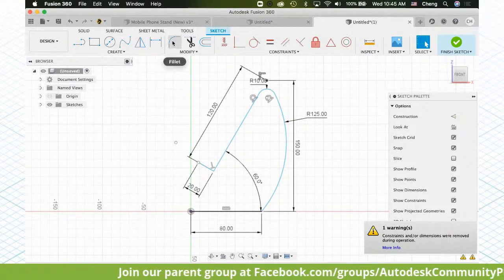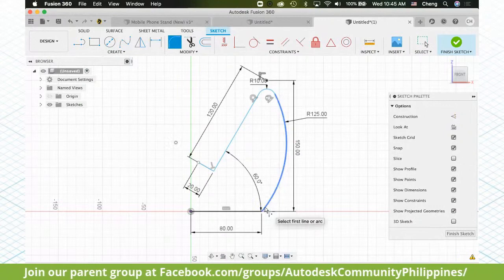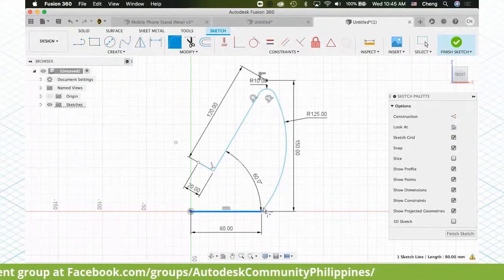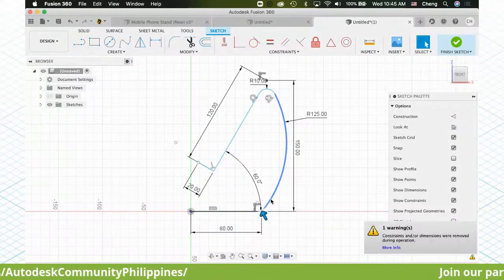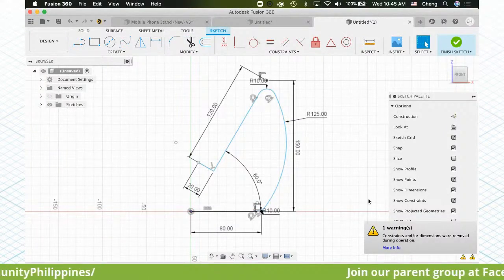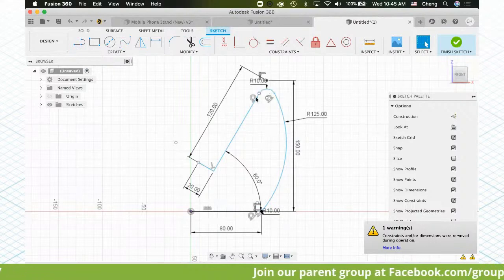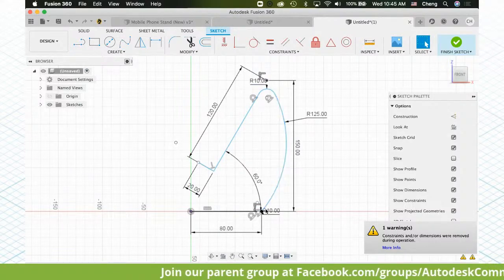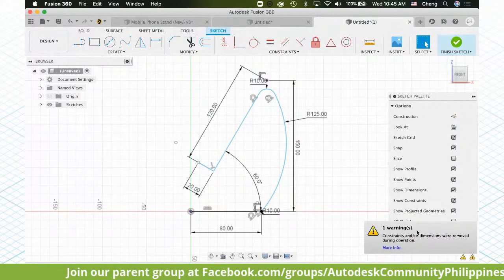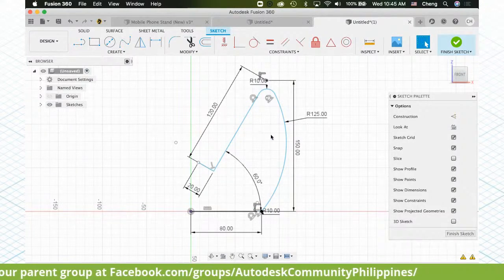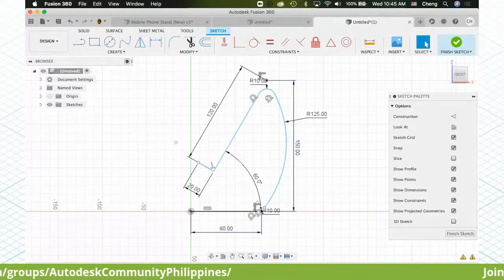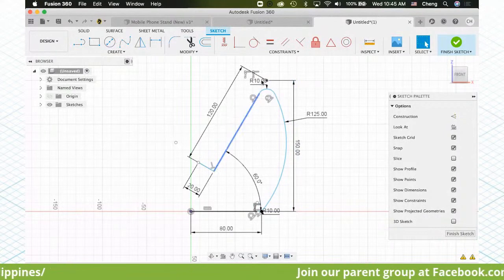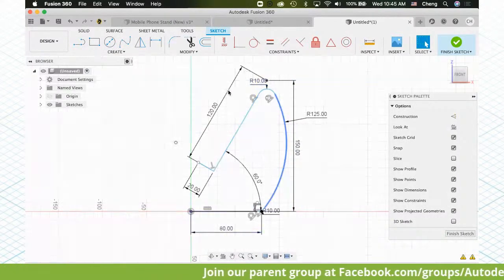Same thing one more time. I am going to do the same thing for the below, the baseline and the arc line, the radius is to be 10 mm as well. So you will see that the model is now being generated. But you will notice that there is one warning sign because our constraints were pre-applied earlier on this 150. Once I already have some constraints, the point went missing. But it's all right. I'm just going to leave it as it is right now.